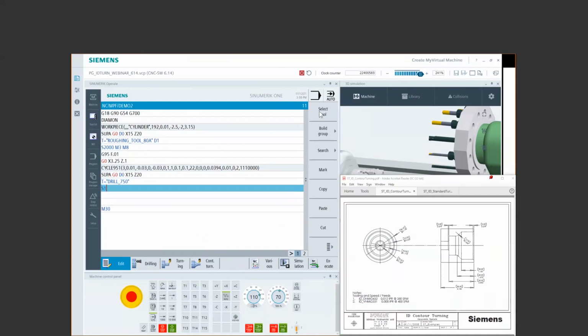Speed, I don't know, maybe we're doing 1,000 RPM. Certainly I wouldn't be running constant surface feed with a drill. Fire up my spindle, my M3, maybe I have coolant, M3, M03, totally up to you, right? It's the same command. Now, I do want to give it a feed per rev of whatever I know I need to run with that drill. And this is the important part right now. This is the big carrot that you've been looking for.